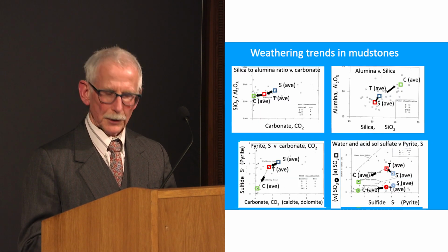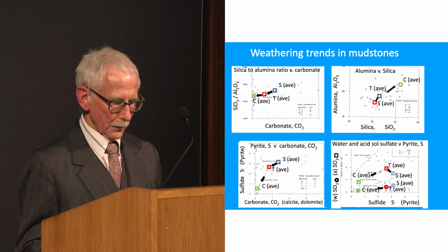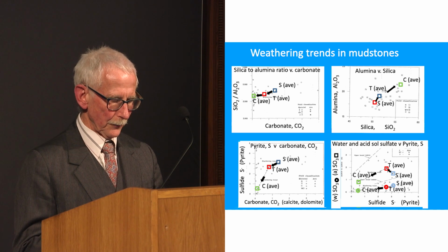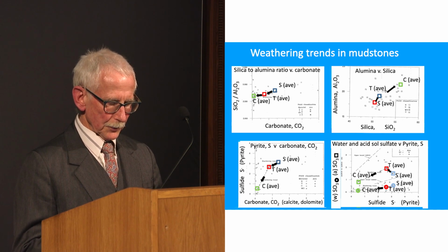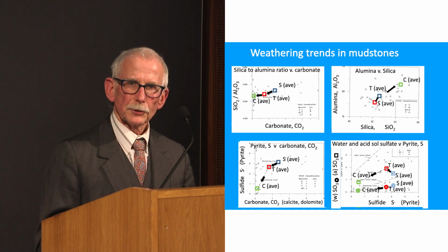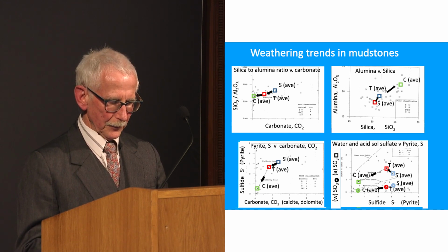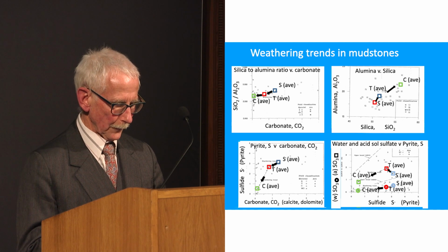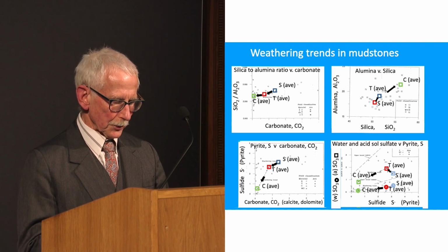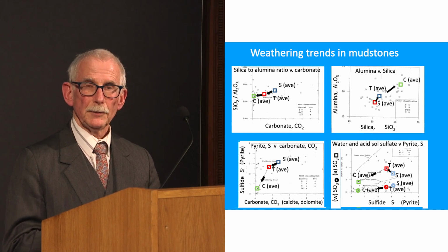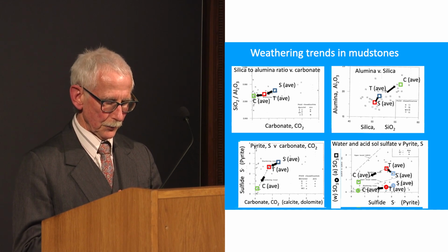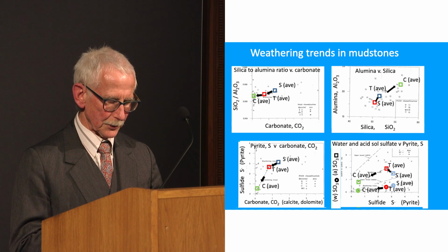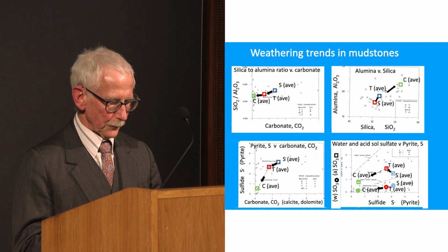During the reconstruction, we carried out regular sampling of the materials being used and carried out mineralogical and chemical determinations on these materials used for reconstruction. The results were very scattered, but by looking at the average for the S, T, and C materials, we could see progressive changes in weathering. These consisted of reduction in the pyrite, although much remained in the T material. This is the material which was used outside the shoulder material. Also, the loss of calcite and dolomite cements, going from the least to the most weathered materials.